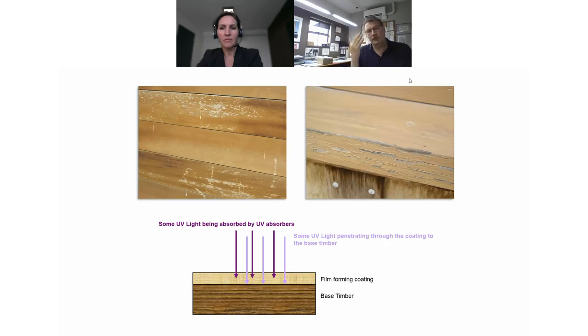So if you question why would I use a penetrating stain that only lasts a couple of years, brands talk about it being easy because it just erodes away. There's no stress on the film pulling it because there's no film there, but you've got much more regular maintenance, but it's easy maintenance. Is that cool? So just be aware of what sort of stains they are. Yes, some of these are still available in the market, but that's what nature does.